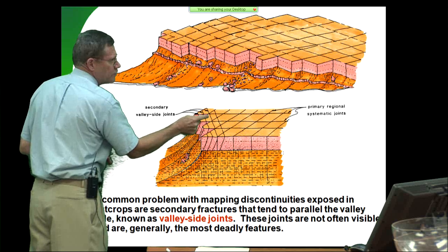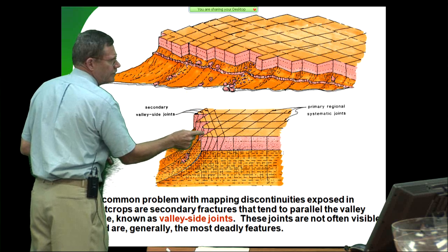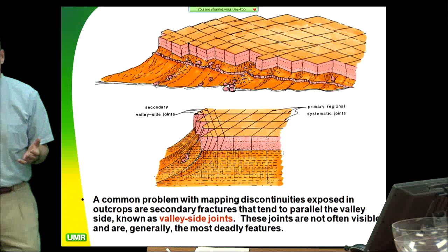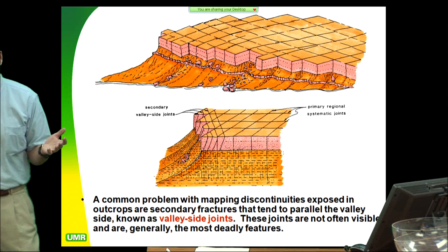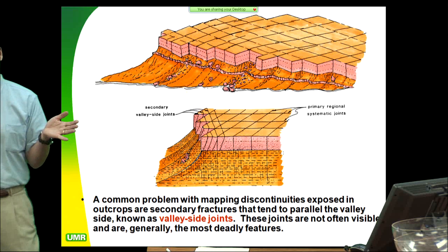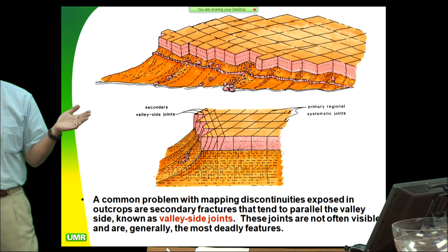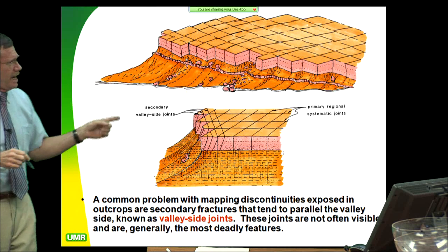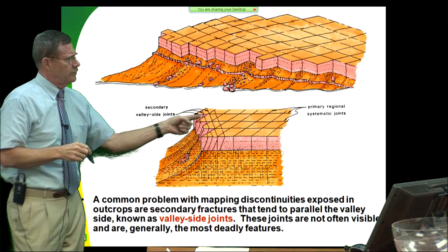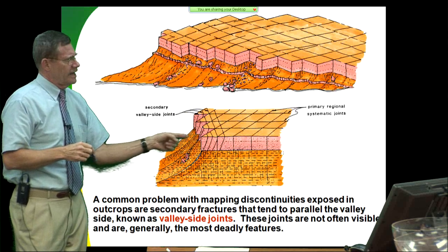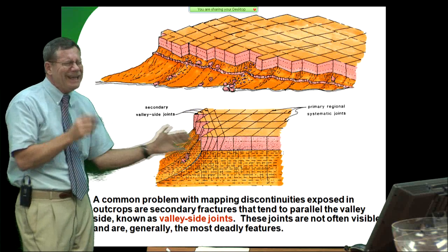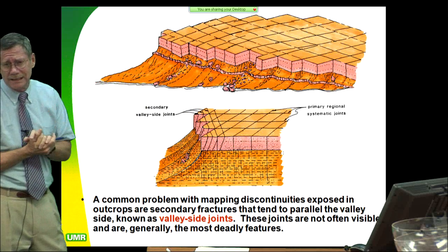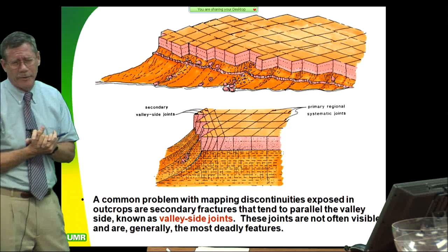We call these re-entries. So when you're mapping someplace like this, you learn pretty quickly when you go out into a new area, there's 3 places I'm going to map. I'm going to map the road cuts, first and foremost, railroad cuts, whatever you got. I'm going to map the channel cuts along the banks of the channel, and I'm going to map any erosional re-entries like this where I can get back in and glean some detail of the 3-dimensional character of the rock mass. Boy, that's so important.